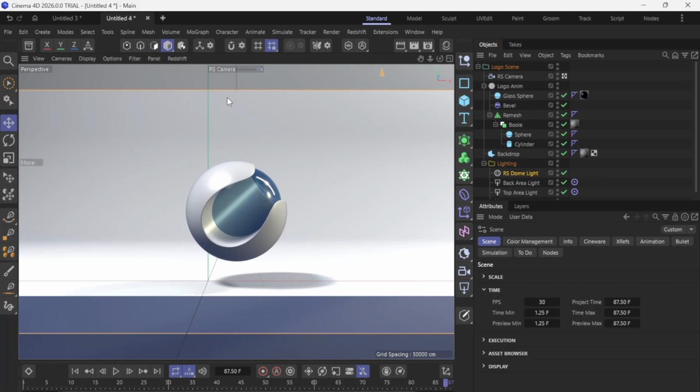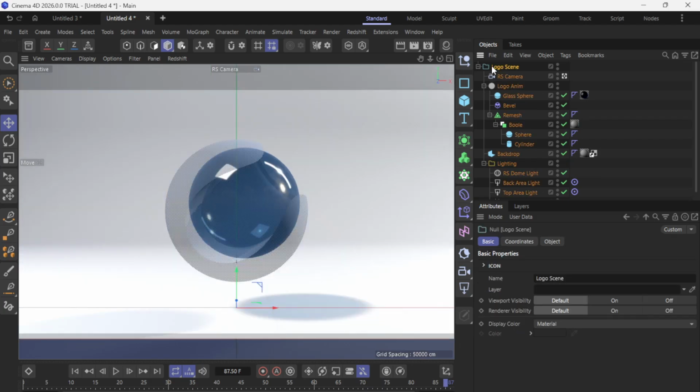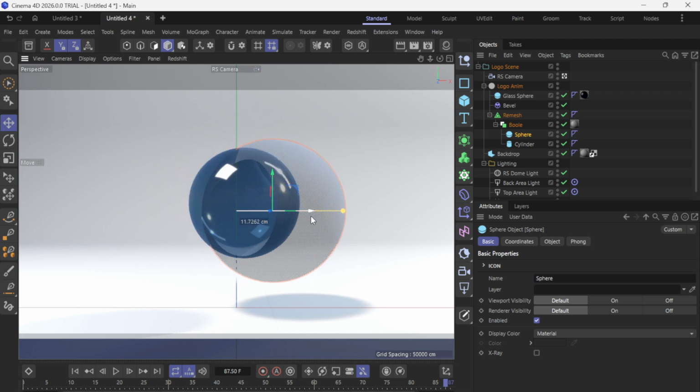Next, add a hinge connector to link the rotating object to the base. Align the connector so its axis matches the direction you want to rotate, X, Y, or Z. The connector is what defines the allowed movement, so its orientation is crucial. Once the hinge is in place, add a motor tag to drive the rotation. The motor tag works hand in hand with the connector to spin the object around the hinge.